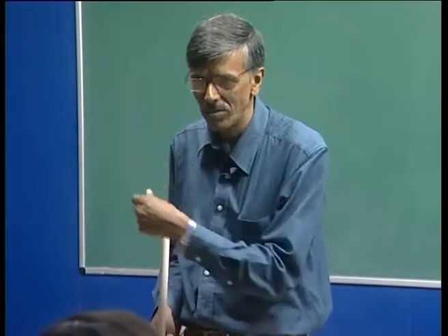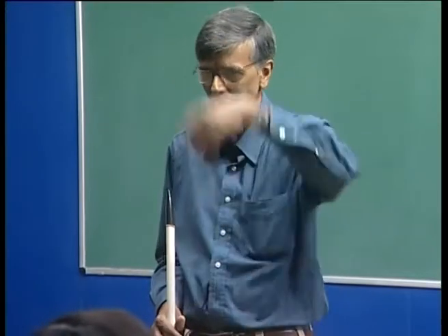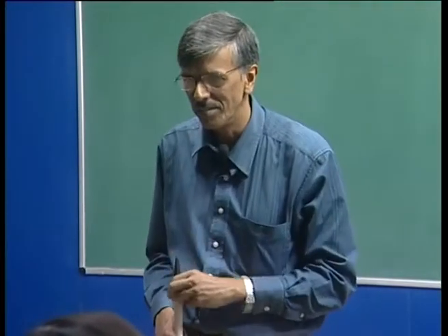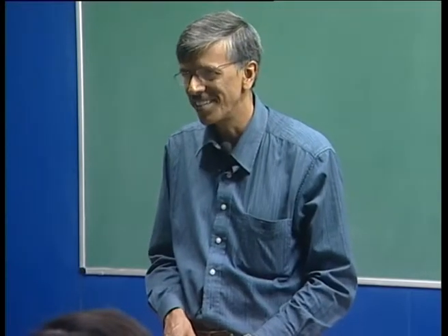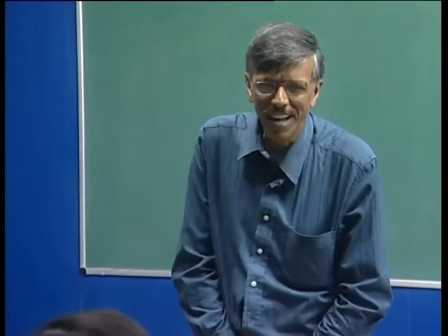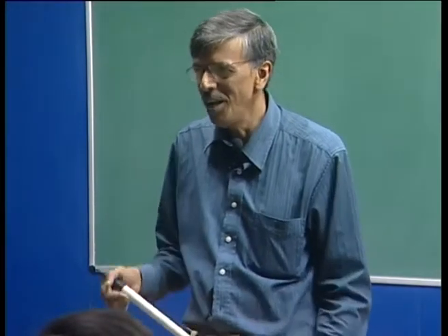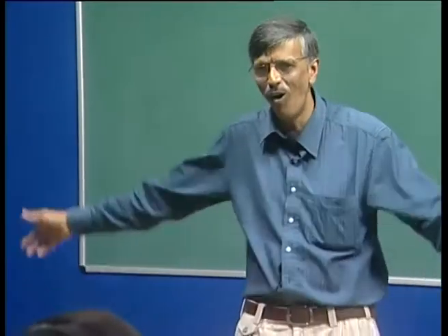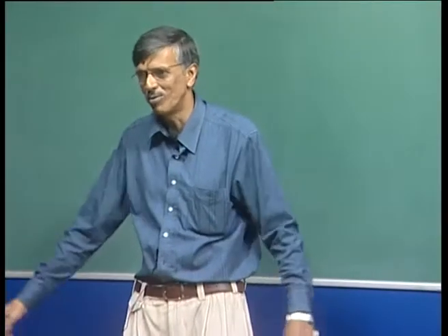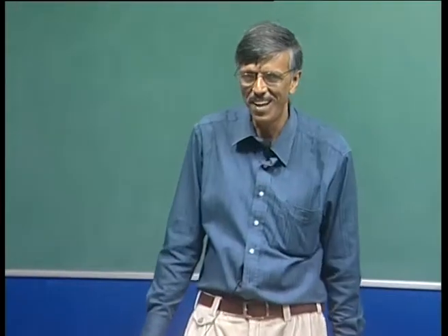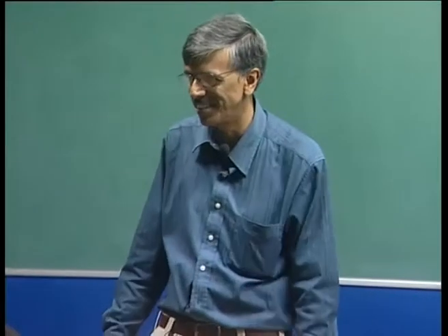2 pi by this. So, 2 pi by 2 pi into 10 to the power 3. So, how much is it? Some 6,000 delta star. How many tunnels in the world are made where your test section is 6,000 delta star? So, if I want to see these long waves, I have to have a facility that long. Unfortunately, there are no such facilities.